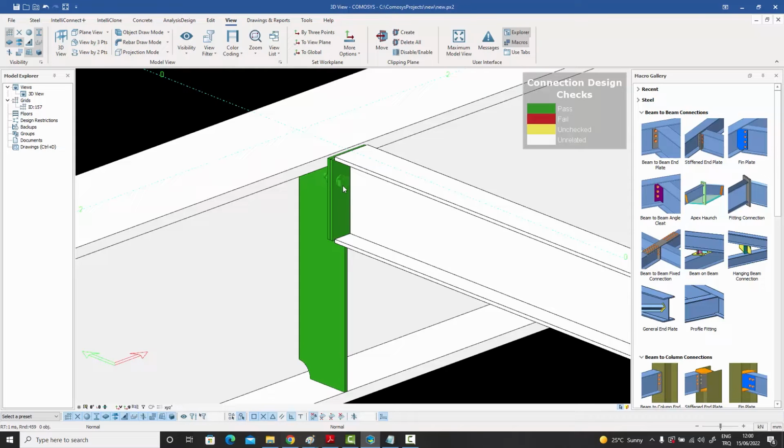It's basically calculating approximately, based on the loads that we've provided, a number of bolts, the thickness of plates, and size of welds. The reason I say approximately is because when you go to the codes, there are a lot of detailed ifs which it goes through.